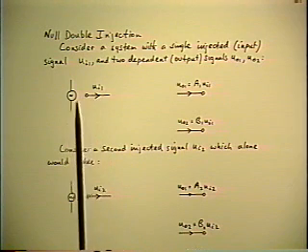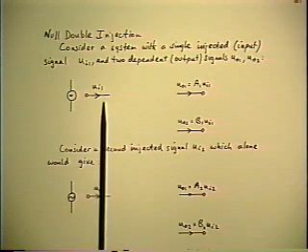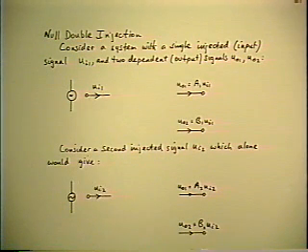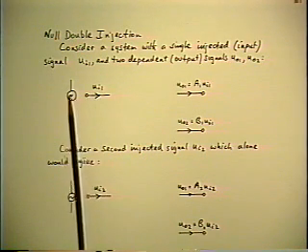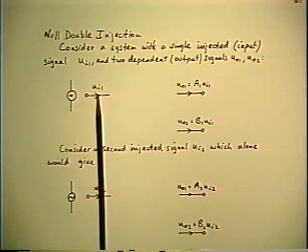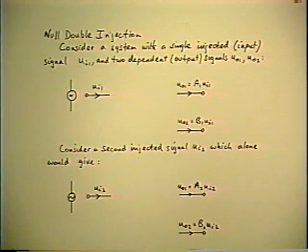We have on the left an independent driving signal, U sub I1. I'm using the symbol U because I don't want to call it a voltage or a current or anything. In fact, it could be a lot more general than that. If it's a mechanical system, the independent input may be a torque, for example, or a force. So U is an independent signal represented by a generator in circuit symbol notation. The sub I means input or independent, and the 1 simply means it's the first one that I'm talking about.